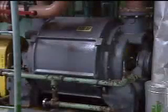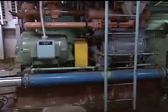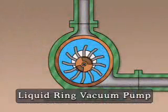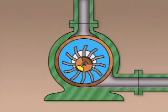Rotary vacuum pumps are also driven by motors or other driving devices. A common example of a rotary vacuum pump is a liquid ring vacuum pump. Here's an illustration of a typical liquid ring vacuum pump. It has a rotor with a number of blades, an inlet port that's connected to inlet piping, and a discharge port that's connected to discharge piping.